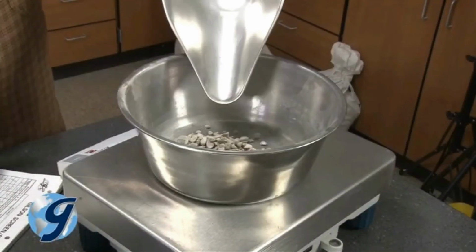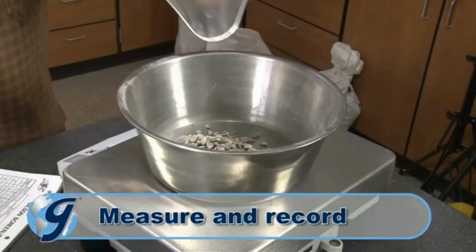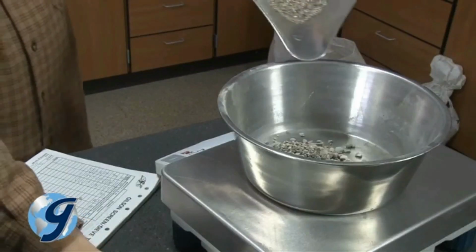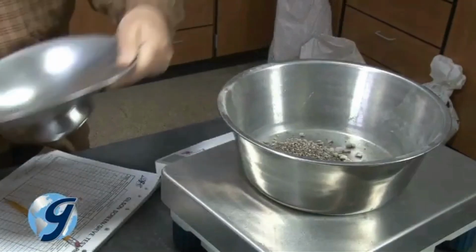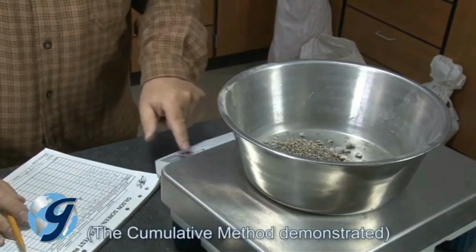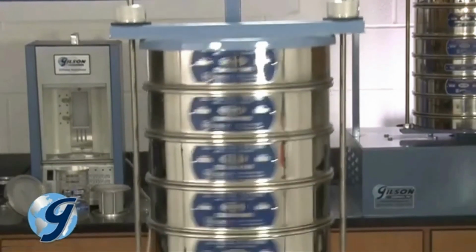Once sieving has completed its course, measure and record the mass weight of each sample size increment on a scale or balance to the nearest 0.1 gram. Repeat this process for each sieve and the sieve pan. The total mass of the sieve sample should match closely with the original mass of the test sample before sieving. If the amount differs by more than 0.3% based on the original dry sample mass, then the results should not be used and the test should be repeated.